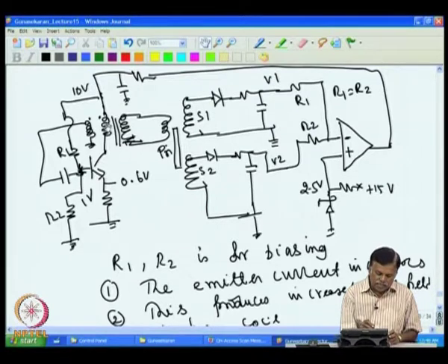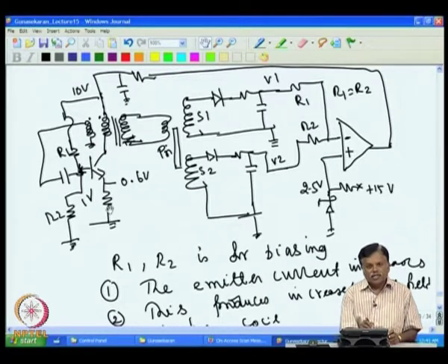So, whatever may be the case, the moment the increase in magnetic field stops, there will not be any induced voltage here. Then whatever induced voltage there was starts decreasing, and this current starts decreasing, then the magnetic field will decrease. A decreasing magnetic field will produce a minus voltage here, and that will reduce this voltage further, and that will reduce the current further, and that will produce more minus.